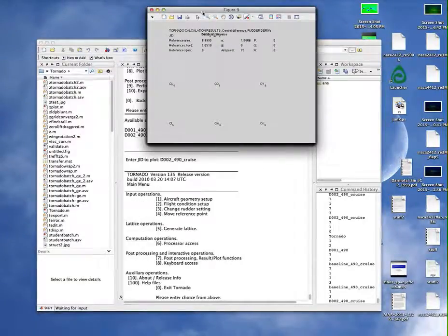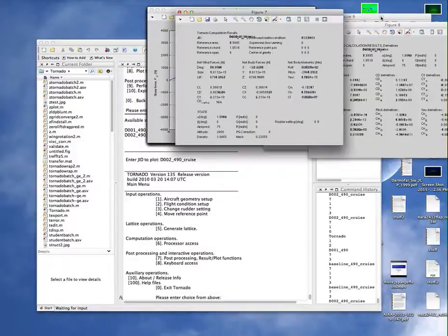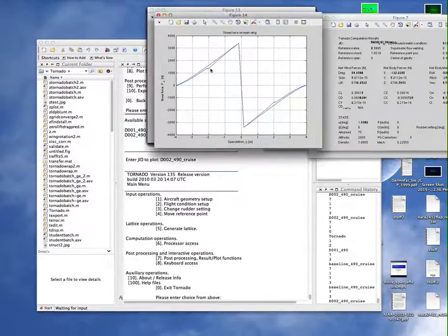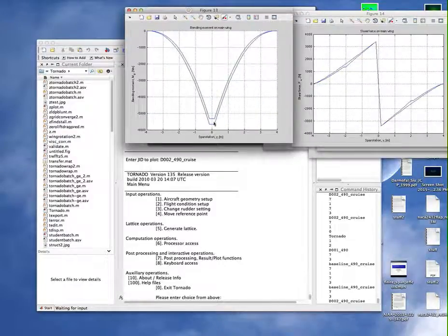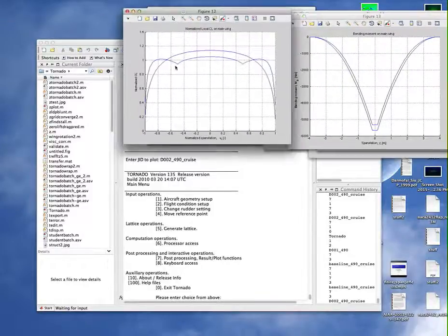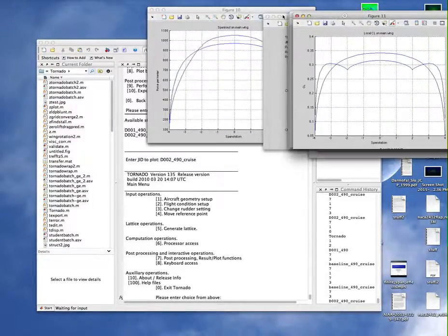Okay, now the line colors are not different, so we have to discriminate between them. We can clearly see the little jogs here, so you can tell which is the 2-section wing here. Here you can't see it, but I know the answer because we wrote down the bending moment. The wing with a smaller magnitude of bending moment is the tapered wing, the wing with taper. This is a straight wing. And if I go, you can clearly see the difference in the lift distributions.